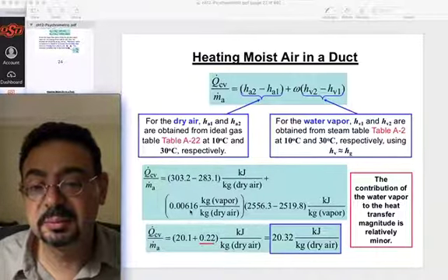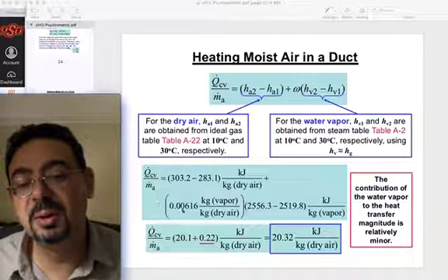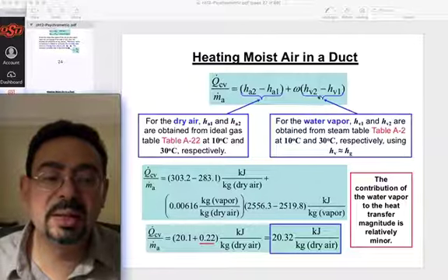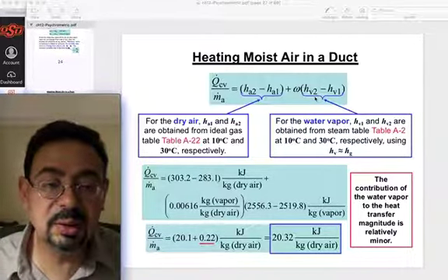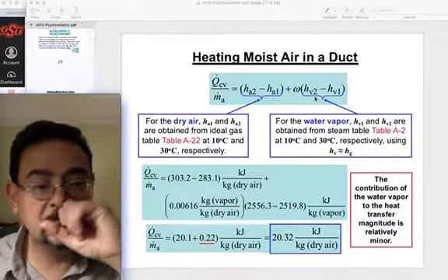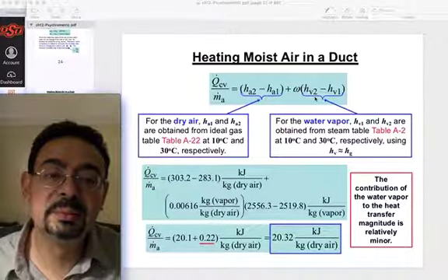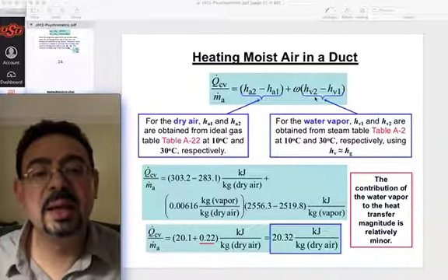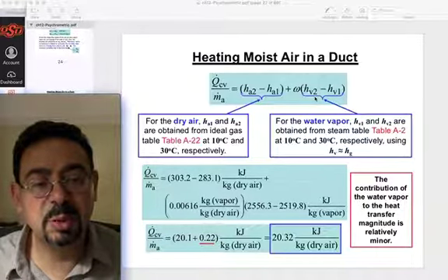and remember I told you the omega is really tiny, right? We said it's of the order of 0.001. Here we go, so it's really small. And now this is the part where, if we have a steam table, go for it, get it accurately. With what? You need pressure and you need temperature, and you'll be able to do it, right? And what pressure? The vapor pressure. And so at the beginning we know the vapor pressure, right?